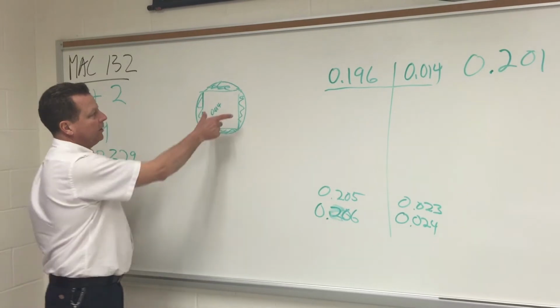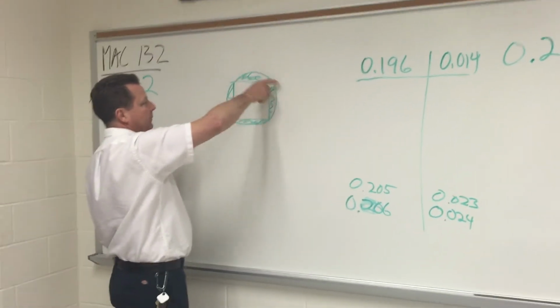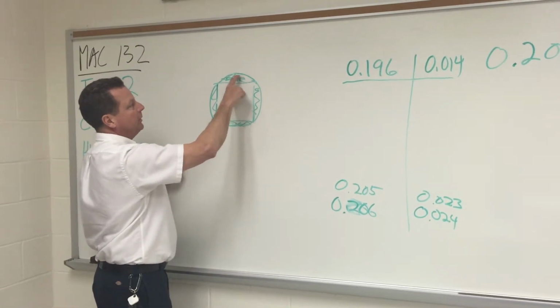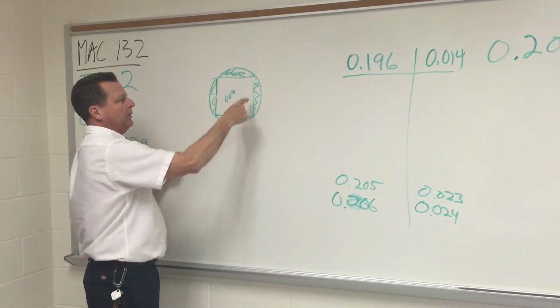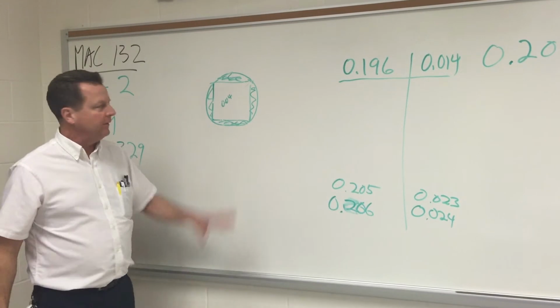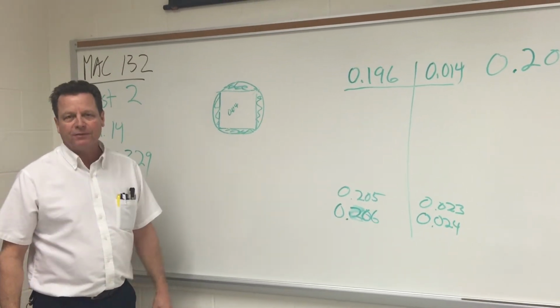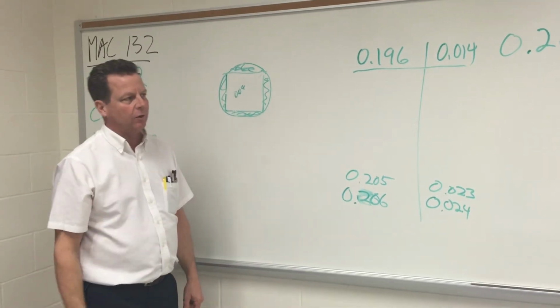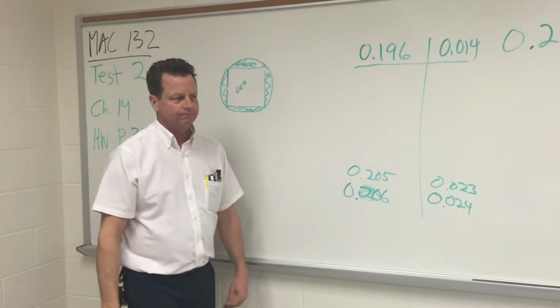So to settle the argument, they went to a 7 thousandths diameter circle, and you'll still be good here, but you'll also be good in these new bonus areas. 53% more surface area when we go to a circular tolerance zone for the position.